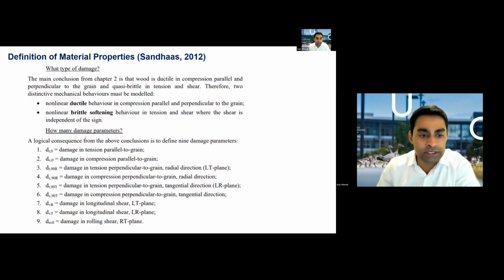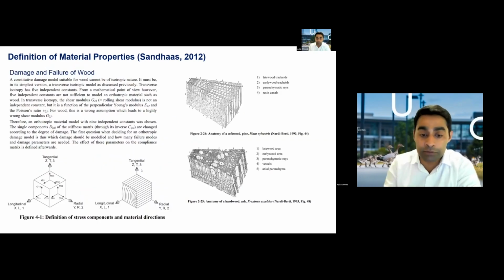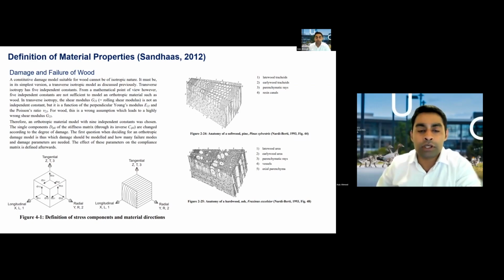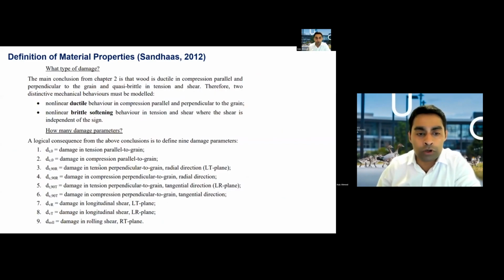However, what they did is they also identified 9 damage parameters, because it's not enough to model the elastic part to get the nonlinear behavior, the failure. To model the failure or damage in this kind of timber, you also need to model the damage behavior, which for steel I'm quite familiar with, as my main work is on steel fracture simulation.